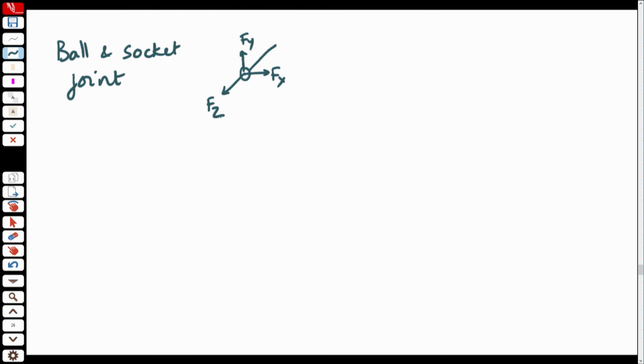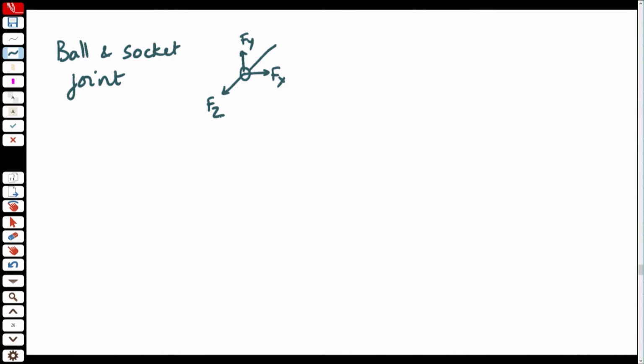Linear movement is prevented. So, a resistive force prevents a linear movement, right. The case of the ball and socket, it does not support moments in all three planes. Okay. So, you have no resisting moment. But we are talking about only 2D analysis. Yeah, this is just for completeness, this is how we map it to what we know in mechanics.